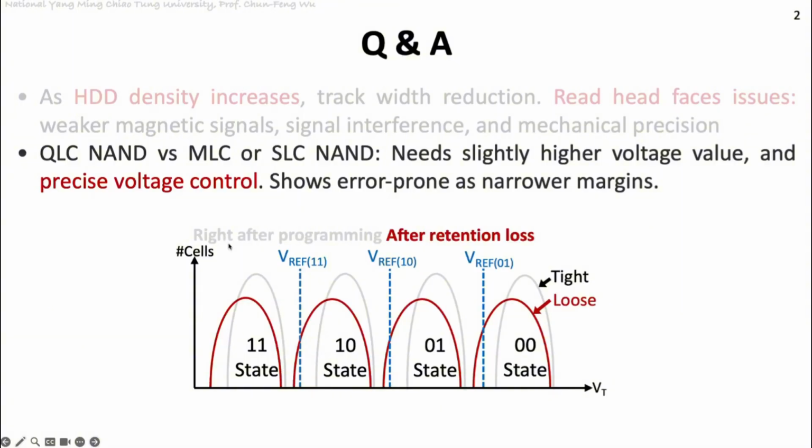Right after programming, you will get 4 possibilities for the 2-bit cells, MLC. Because using almost the same voltage range, from 0 to VT, you actually need to decide more labels here. So it does increase the challenge of how to precisely control the voltage, and if there's an error, how to deal with it.